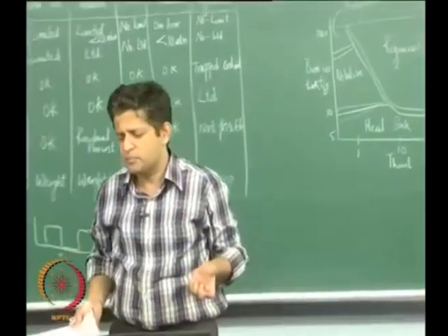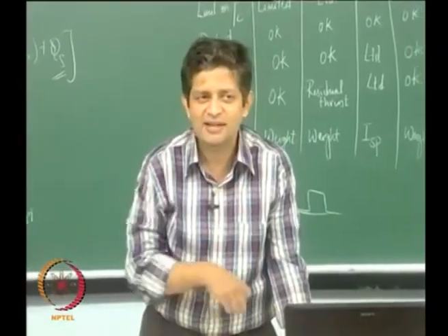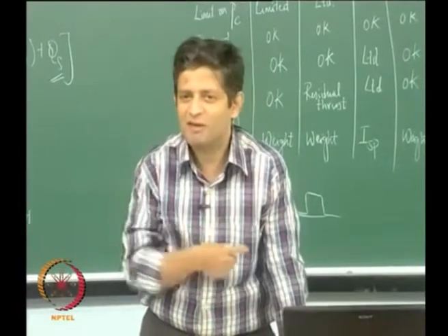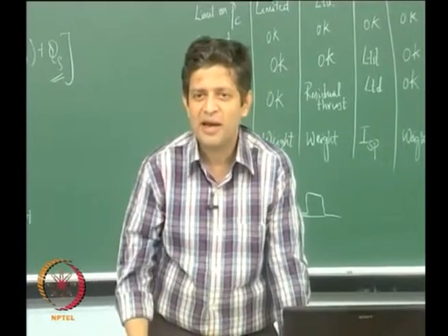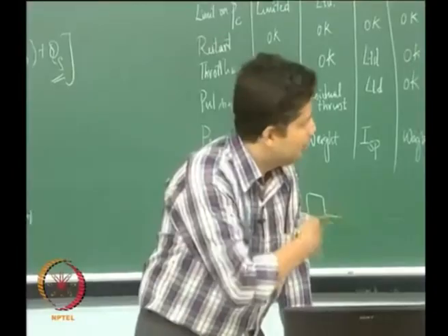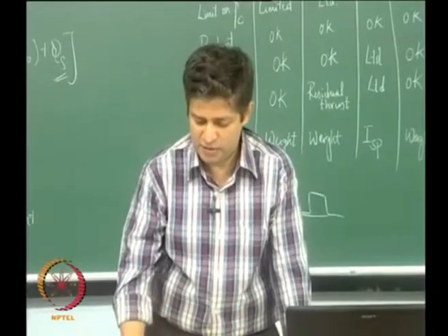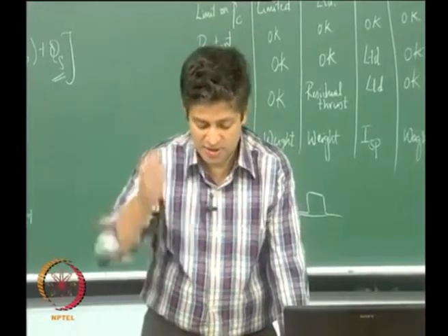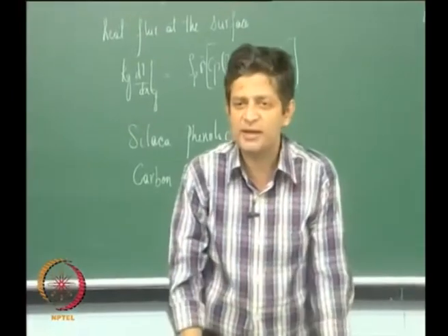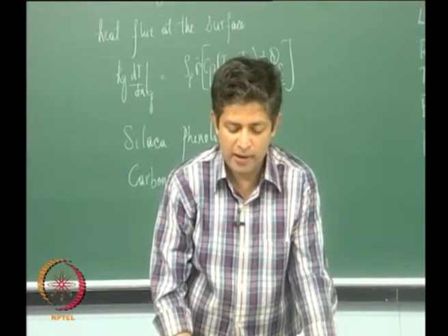And I have not indicated where film cooling is. As I said, if you are using a liquid engine, it can be used everywhere in this domain. It is to add some kind of redundancy, and therefore can be used all across the domain. Okay. So this completes our discussions on the various cooling techniques to cool the rocket motor nozzles. Now let's look at